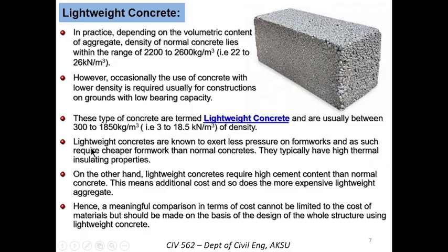Now, lightweight concrete is known to exert less pressure on formwork, and as such requires cheaper formwork than normal concrete. Because the density of concrete is less, you might not need as much formwork as you will need in normal concrete. They also typically have higher thermal insulation properties than normal concrete.